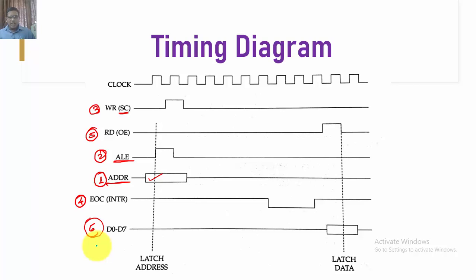Okay. So the moment at which I am going to enable this ALE, depending upon the configuration of the address lines, one of the input channels of the 0808 is selected. Now the analog data is taken as input. Input where? In this 0808 IC, right?